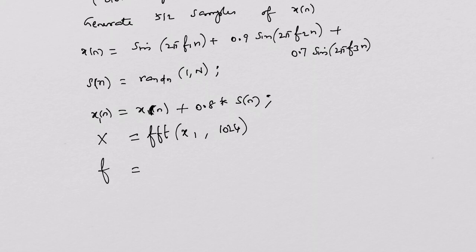To view the spectrum, let's define a frequency scale starting from 0 in steps of 1 by 512, 2 by 512, 3 by 512, 4 by 512, etc., till 512 minus 1 divided by N, which will be the set of tick marks available on the scale. Let's view the spectrum and we shall downsample it. Also, we shall work with decimate and see the spectrum.